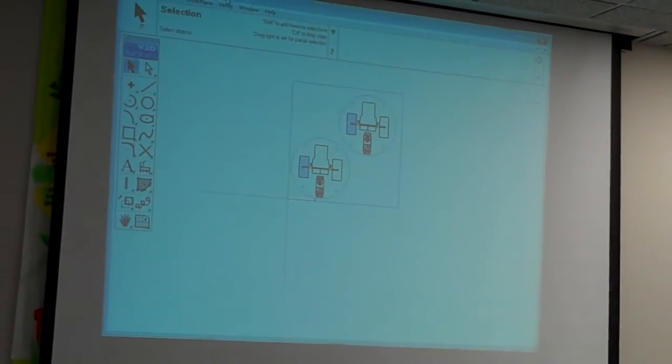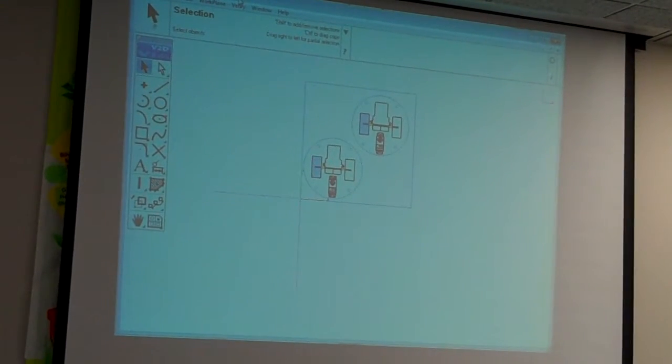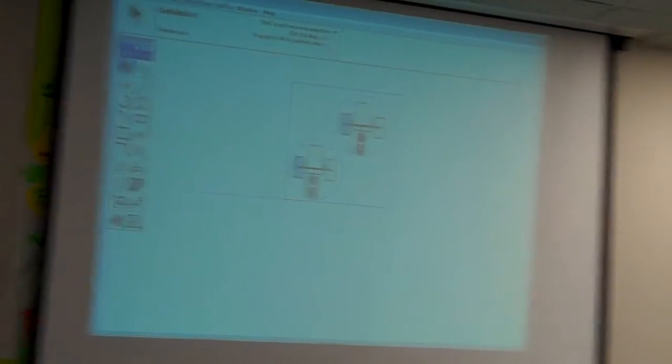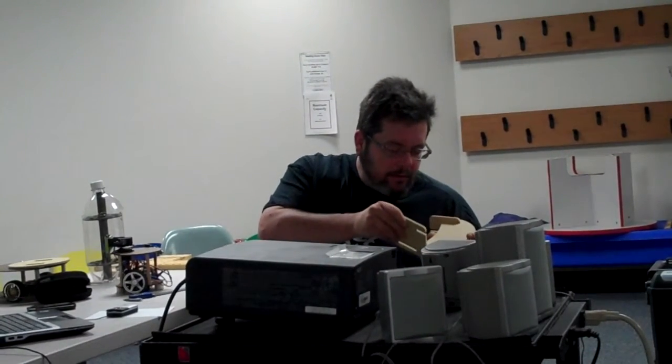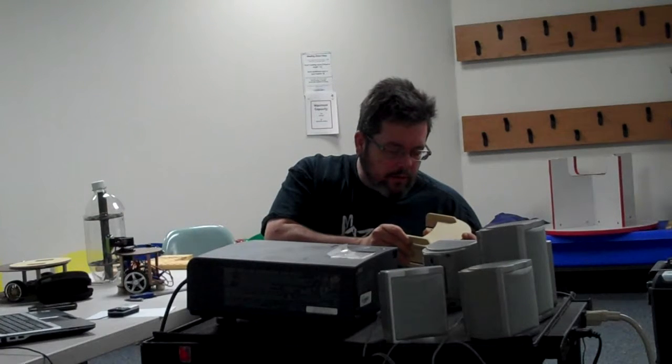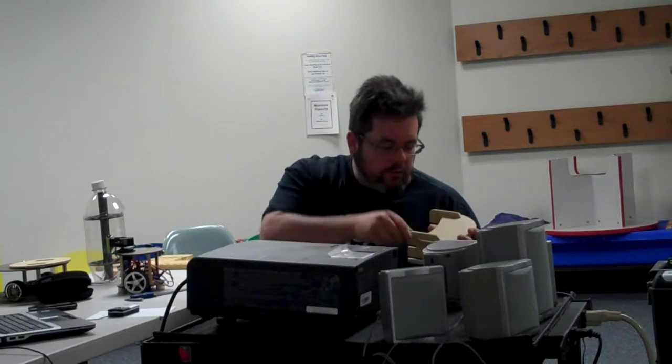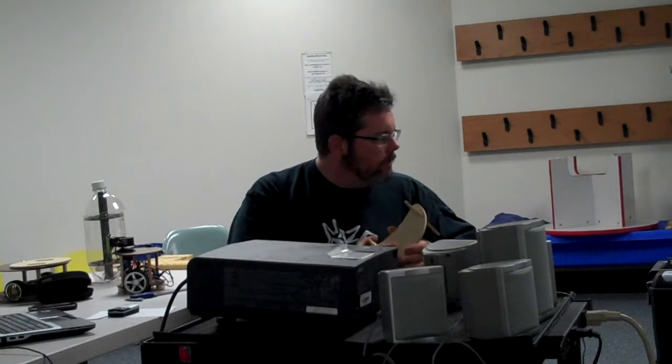I do a lot of things that are slotted, so this takes a little time to get used to. Even though it might be a 1/4 inch material, when I cut that slot, it needs to be slightly less than a 1/4 inch, so when the tool goes in, it still fits relatively snugly. So there's a little experimentation to do there.